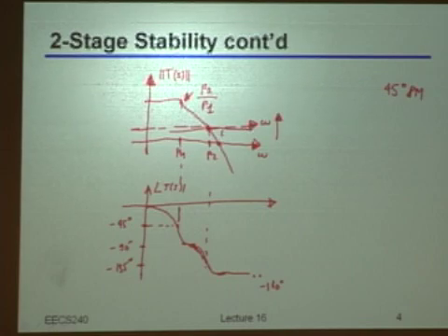So I want to decouple this stuff because, I mean, how far can the poles be? Like, I don't know, 10 times, one 10 times than the other or something like that. And then I would have at most a gain of 10, right? But this is not the case, because my static accuracy in the closed loop amplifier requires maybe 1000 or something more for the gain. So at the end of the day, I should go for smarter ways of gaining phase margin.